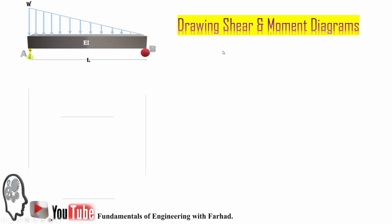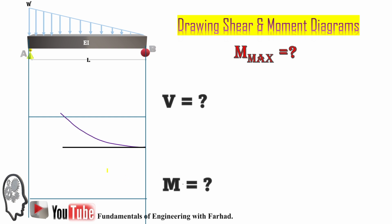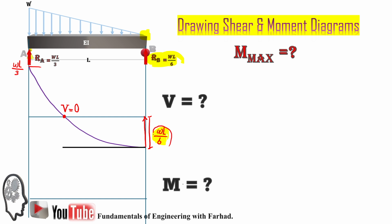In drawing the shear and moment diagram, you can easily see the shear diagram simply starts with the value of WL over 6, which is here. There is no loading here, as you see. So the support reaction brings the shear diagram back to 0 by the amount of RB.